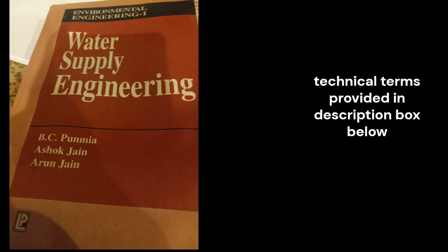So first, the design elements are calculated here: required outflow rate, water loss, design average flow. The second stage is computation of settling velocity of minimum size particles. Stokes law is used here. The third step is determination of surface overflow rate.